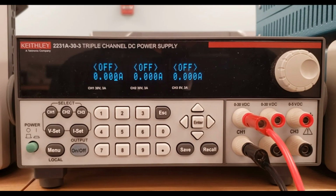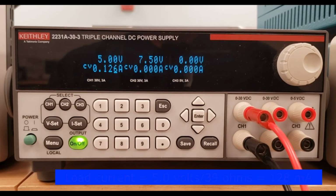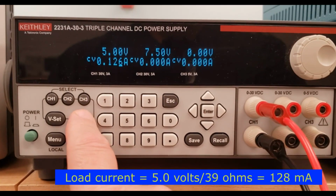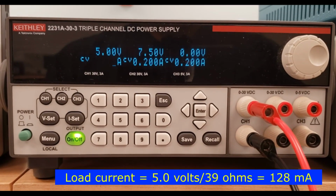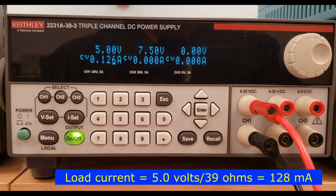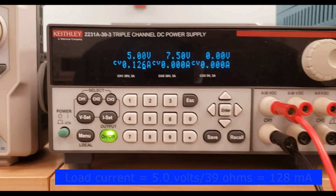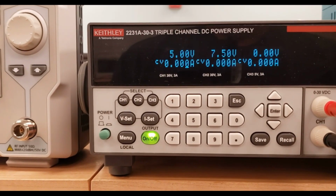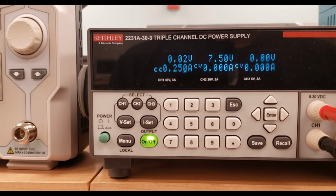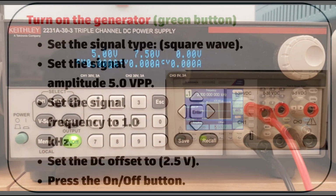I've typed it in directly on the keypad and then hit enter. Eventually it'll stop flashing and it'll show you the current output. So I want to turn the output on. So it's showing me that I have a voltage of 5 volts. And my current limiting is set to 250, but it's drawing 126 milliamps right now. And I believe I'm going to simulate a short circuit by shorting the alligator clips, and that gives me a constant current of 250 milliamps.